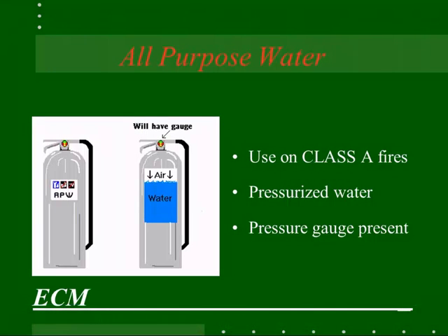And then here's this guy. You really don't want to use this. It's only good for paper or wood. You don't want to be spraying water on an electrical fire, obviously. And if you're in a dealership and you have an oil fire, it's going to be just like a fire at home with a grease fire. If you spray water on it, it's just going to spread the fire. So that's on the quiz. That's why you don't want to use water in that situation. If a fire does break out, grab the extinguisher. Don't try to take a water hose that might be in the back of the service area for an oil fire.